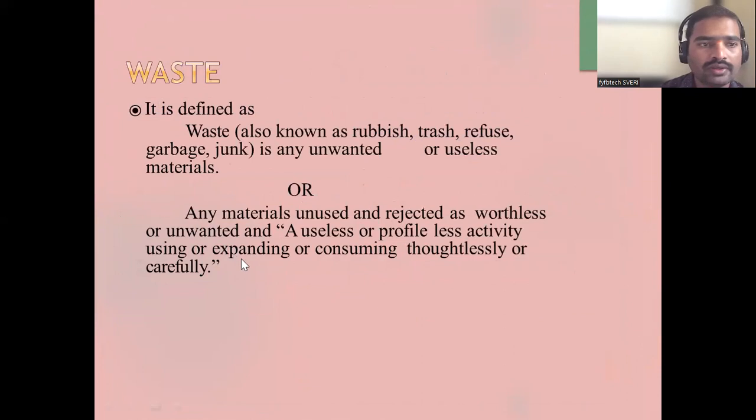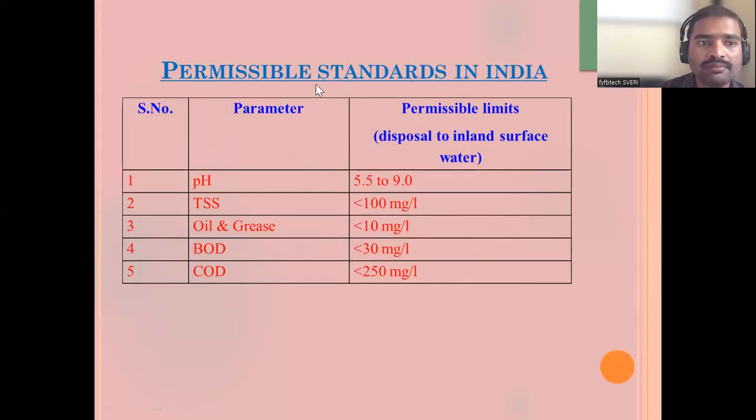Finally, your wastewater has permissible standards after the tertiary treatment plant. Industrial waste has hazardous material, and it is not possible to treat it to 100% pure water. Your waste has some components that vary in range. The pH range will be 5 to 9. If the effluent has a pH of 5.5 to 9, then it is allowed for disposal.